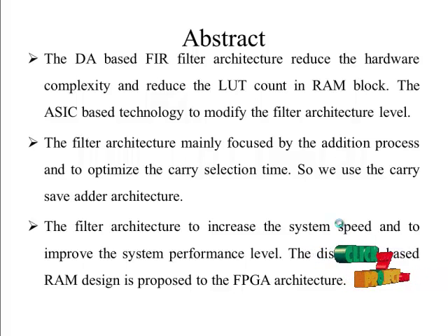Finite impulse response filters, most fundamental components in digital signal processing, are generally implemented on dedicated hardware rather than software for high-speed computation. Because of the requirement of low-power, high-speed implementation of FIR filter design in various embedded applications, it is necessary to design reconfigurable filter architectures based on power or resources consideration, or simply to implement new functionality on the run. FPGA is one such platform which allows adapting hardware resources to meet time-varying requirements in power, resources, or performance, and at the same time maintaining a good speed of operation.